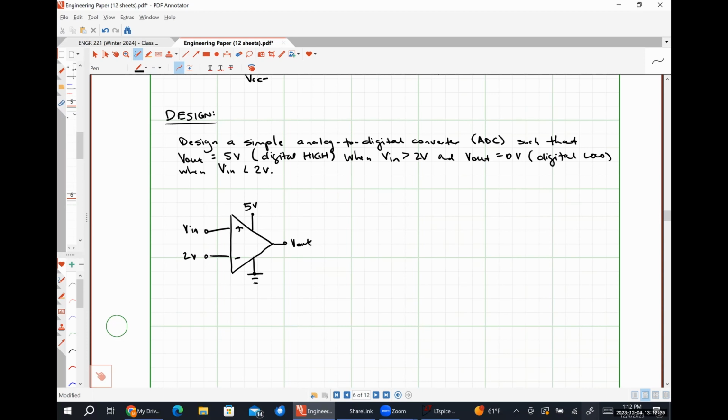So, five volts is a pretty standard voltage for digital circuits. 2 volts, not so much. So, how could we get 2 volts to use as a reference? What I mean by this is, right now, we would need access to a 5-volt source and a 2-volt source. So that's 2 pieces of equipment that we would have to have access to physically implement something like this. I want to eliminate one of those power supplies.